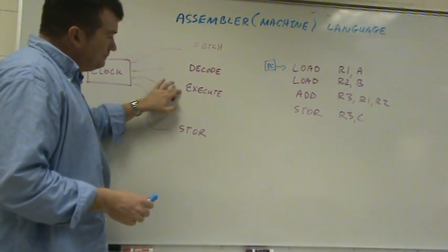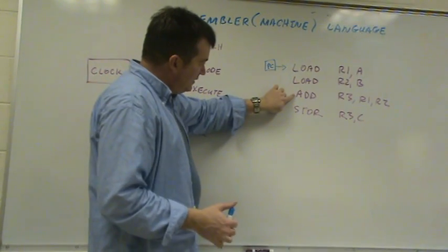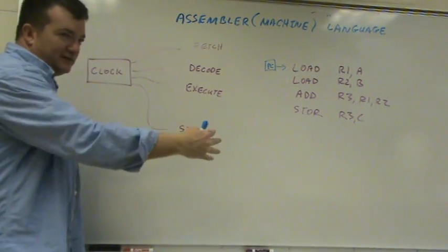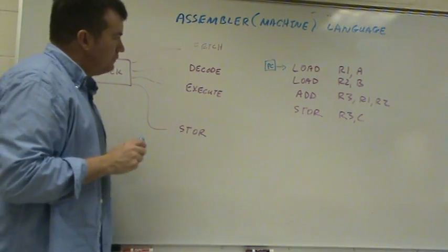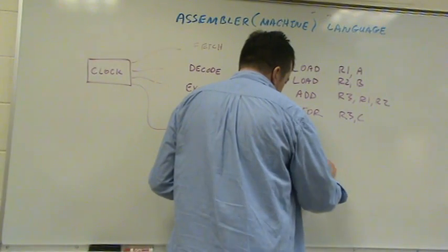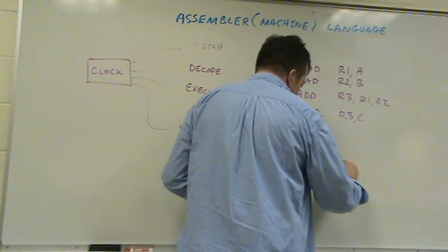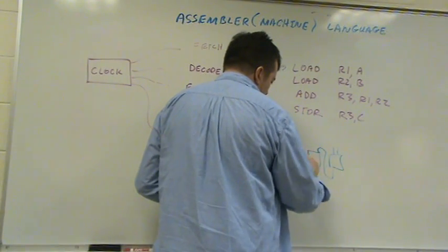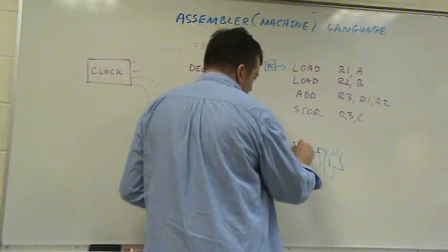Now at this point, if it was an add instruction, there is a piece of hardware that now has to begin some process. For example, we talked about the full adder, right? If you remember, the full adder was a series of adders hooked up to each other where the results of one went into the next one, a rippling effect like this.